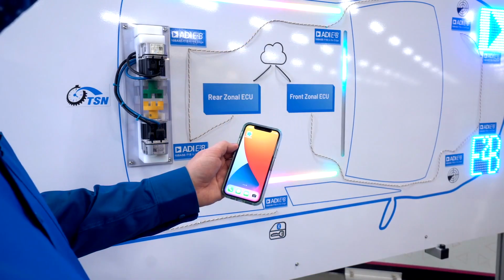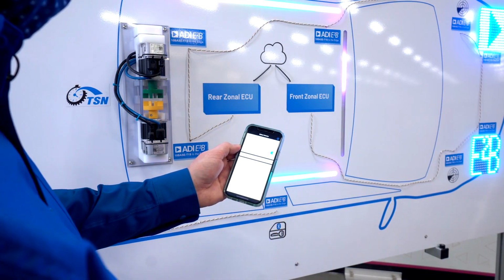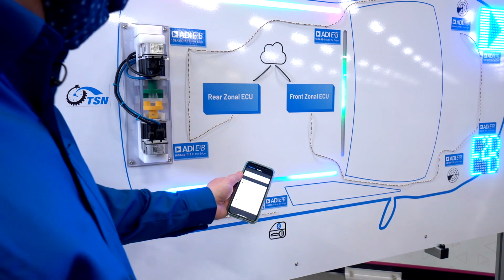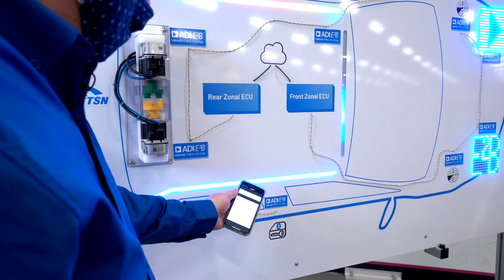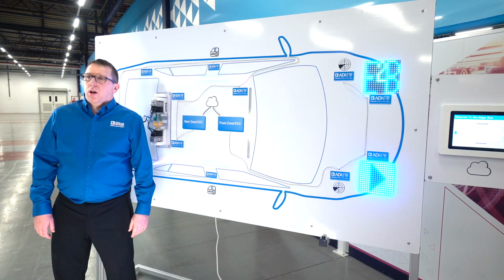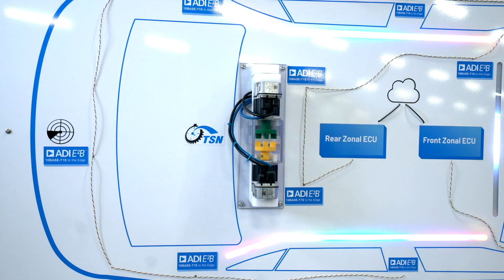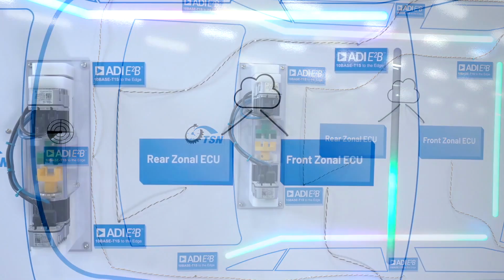Next, on the rear zone, we show BLE modules used for keyless entry applications. I connect my cell phone to one of these BLE modules, and the ambient light LED strip indicates my phone distance to the car. As I move, you can see the change in distance reflected by the lighting strip. Again, both the BLE node and the lighting node do not use an MCU for Ethernet connectivity. The radar module in the back is working in presence detection mode. This acts as a kick sensor to start the 2 motors on the same 10BASE-T1S network. The central ambient lighting strip also reacts to the presence detection.